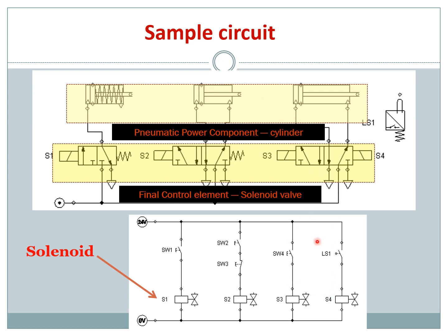Okay, and one more, when you have switch 4 active, you press switch SW4. Okay, S3 will be magnetized, the coil will switch state and the cylinder will move forward, and you have a switch here. This kind of switch is similar to your roller valve, but in an electropneumatic circuit you are using a reed switch, or you can use a sensor.